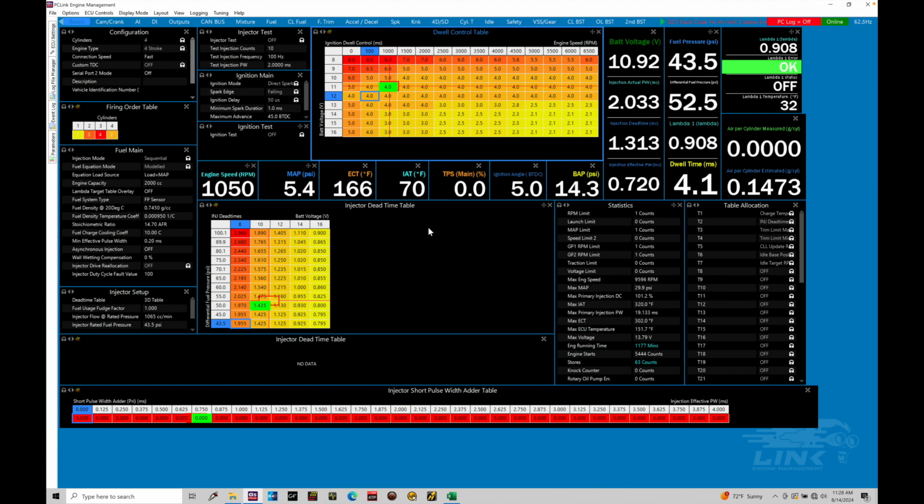So speed is really important to have coming into the Link. It's really easy to set up. What we're going to do here is take a look at setting up a vehicle speed sensor as well as a wheel speed sensor here for our programming. And then depending on what you're working with, you'll know exactly how to do this and configure the software here. There are some little bit confusing things that can go on in the programming. We need to pay attention to those details so the Link understands what it's looking at with the speed sensors.